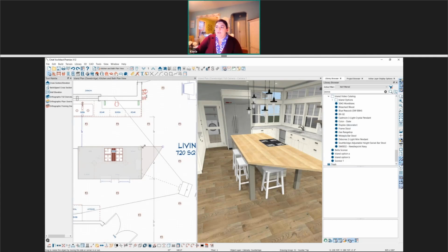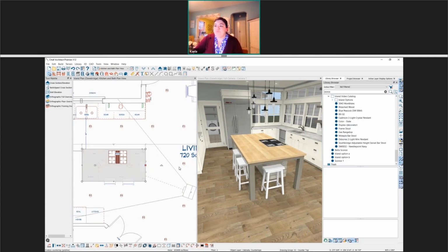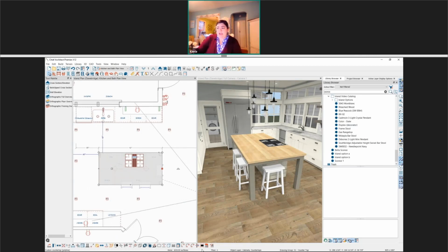Okay. So now that I have just one that's going to be easy to add curves to, I'm going to select this polyline, and down in the edit toolbar, we have a fillet lines option. Before you fillet all the corners, you can set the fillet radius. That's going to do just a basic round curve, so we'll set it fairly small to begin with.